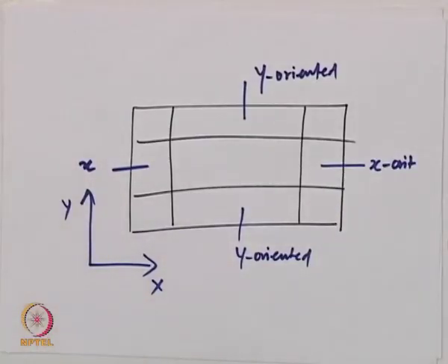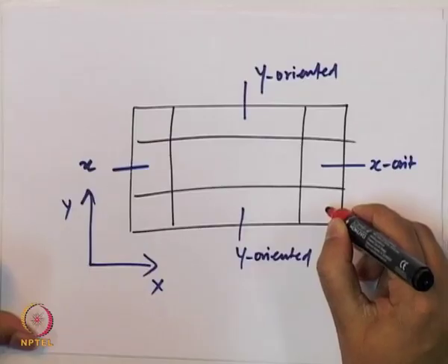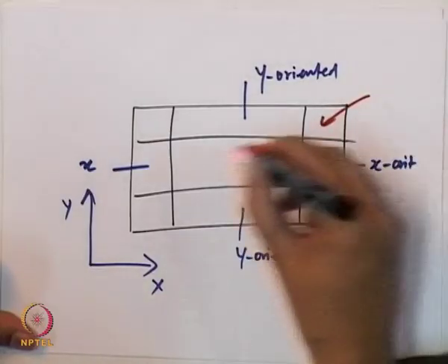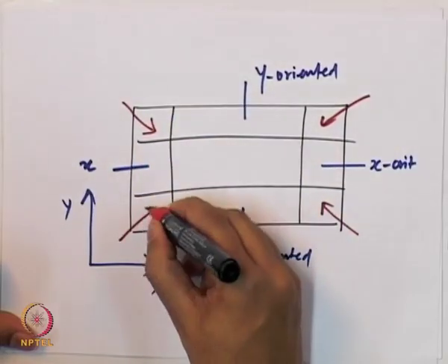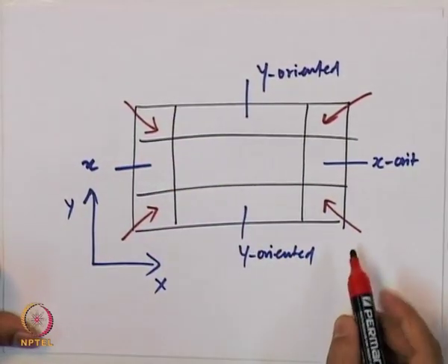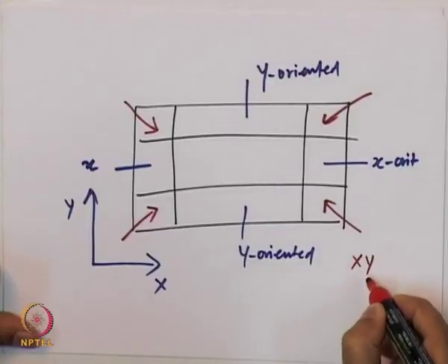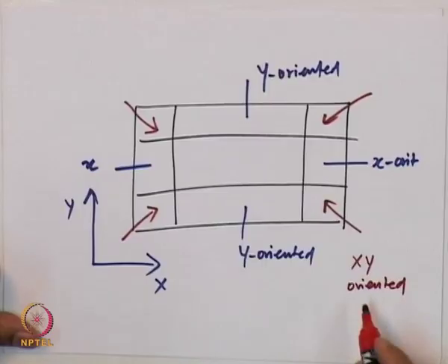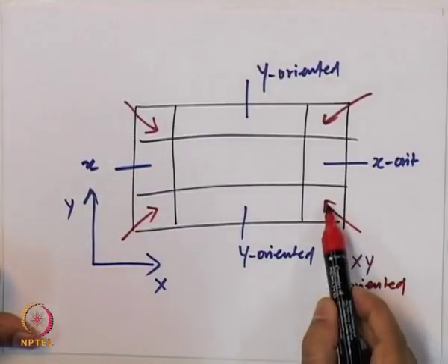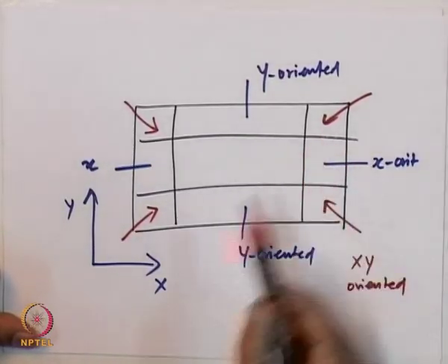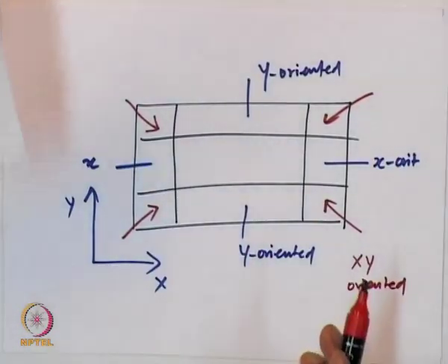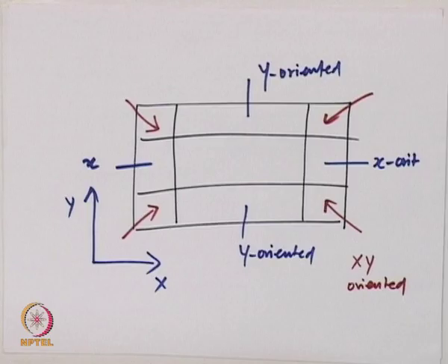I think we saw this also in our earlier lectures in the finite difference method. So this one, this one, this one, and this one are special cases. They have both x and y oriented, so we have to handle them specially, and we have to compute different fluxes. This we can avoid when we go from the split formulation to the uniaxial formulation.